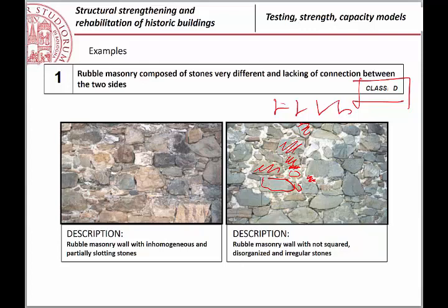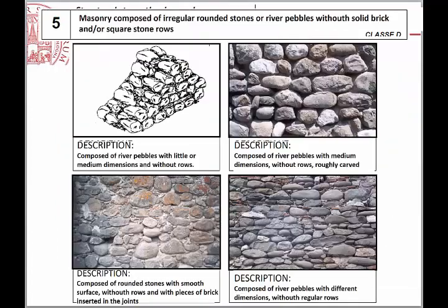So it is like the mortar is almost not useful at all, because the blocks are just put one over the other over small surfaces. Why? Because the mortar is deforming a lot because of its very low elastic modulus. So this is one of the worst cases that you can have.